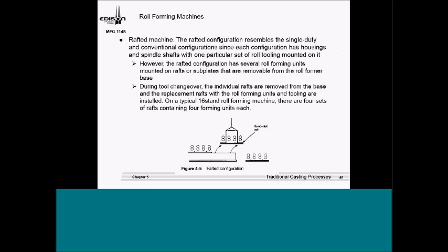Okay, going back to this again, one other thing that I show them is when you're looking at progressive rolling dies, the company that we go and see, Jackson Tube, I want you to picture those dies in different sections. So it's almost like something like this, but they go in at 90 degrees. If you have a section, for instance, you may have a roll that's starting to crack, it's making some noise, or it's indenting the material the way it's not supposed to, something got into it. They'll shut the machine down. So when they shut the machine down, they are losing money.